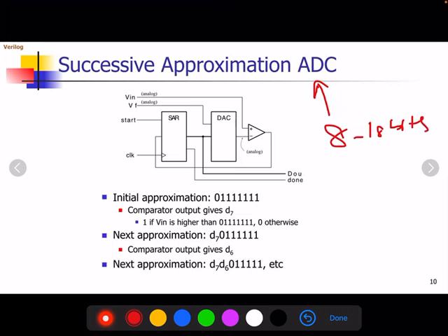Likewise you can have a look at that. SAR followed by DAC has been connected over there. In the successive approximation type ADC, the signal can be converted, and a digital to analog conversion is done over there. It consists of a comparator, because signal comparison has to be done. The analog input, analog voltage reference, start signal and clock have been provided.